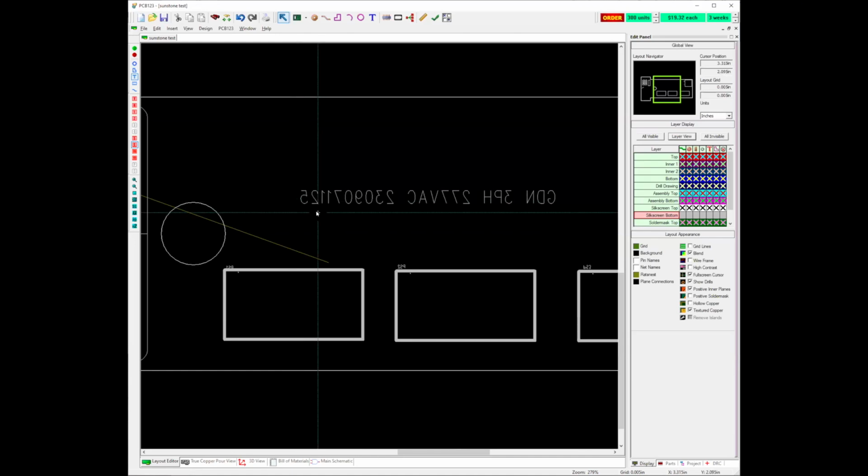I save the file with that name, then I select that text in the file name in my file system, copy it, Control C, and then I open my design. I set my select filter to text only with assembly or with silk screen layer, so that I can put it on my boards on the bottom typically. But if you only want to pay for one layer of silkscreen, you can always put it on top. But I've just put it on the bottom to get it out of the way of everything, so it's easy to find on the circuit board downstream.